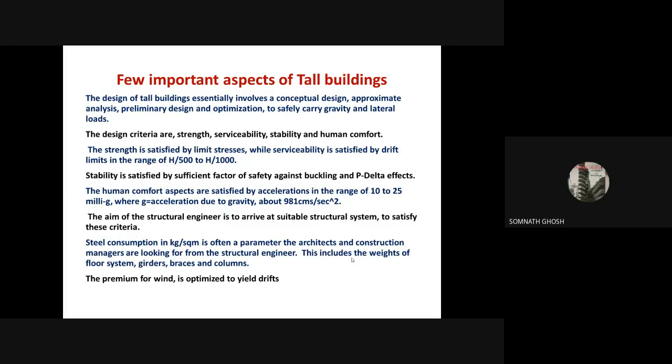That means we have to make it as light as possible from the earthquake point of view. Again, if you try to do that, wind may be a problem for you. And again, if you manage wind and earthquake both, but your client is not happy because he is expecting steel consumption on the lower side. So it's a real challenge.